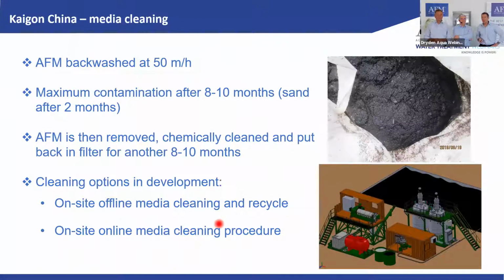They're actually working with 2 different systems now that they are exploring. One is an on-site offline media cleaning, so they shut the filters down, they take the media out, they clean it, they put it back in. And the other thing they're experimenting with is an online media cleaning procedure that would allow them to mechanically and chemically treat the media. Exactly.